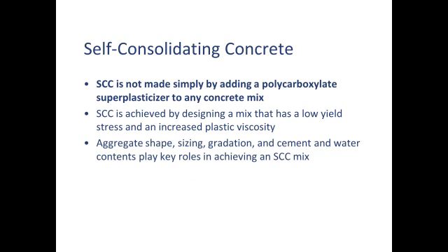And since we're talking about admixtures and we're going to be covering polycarboxylate superplasticizers, I wanted to mention that there's a misconception that you can take any kind of mix and turn it into a self-consolidating mix simply by adding more polycarboxylate to it. And you can't do that. You can get very fluid concrete that way, but it may not be self-consolidating. And sometimes you don't need it to be. Don't think that you have to be making this. Sometimes just grabbing your casting table and shaking it is all the energy the mix needs to flow. That's not self-consolidating if it takes external energy. So it's nice to have this, but it's not necessary.